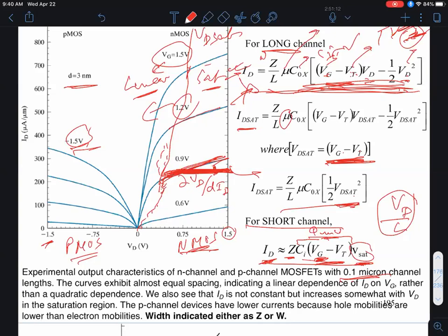That turns out to be a problem from a circuit layout point of view, because in CMOS, as I mentioned, you typically will have both N channel and P channels always work hand in hand. It'd be nice to have them have comparable drive currents. Because they don't, you're generally forced to make the width of the P channel devices roughly twice the width of the N channel devices, to compensate for the lower hole mobility.